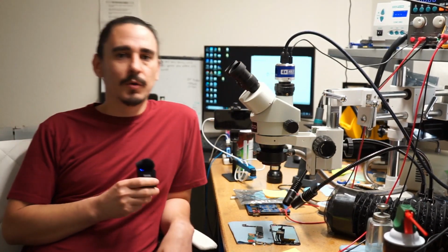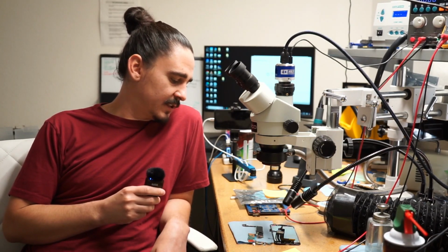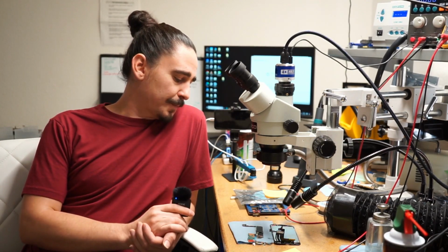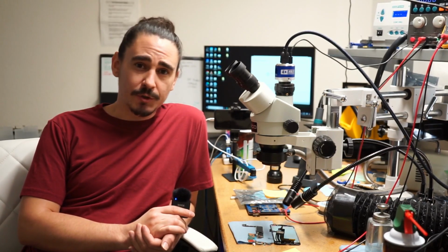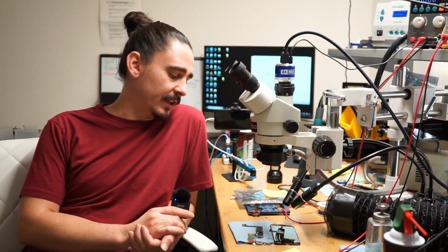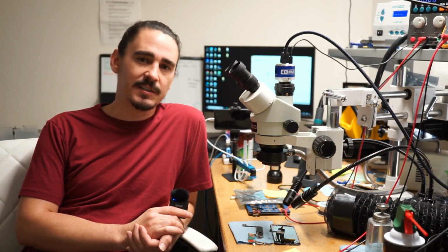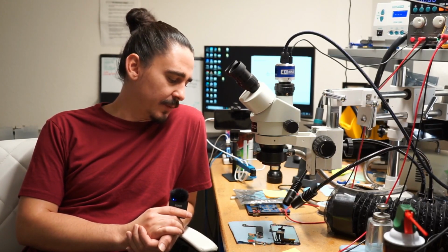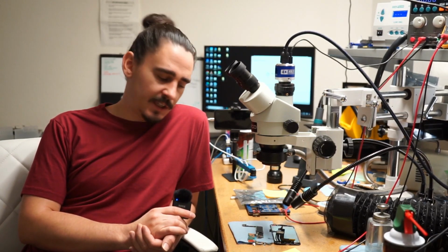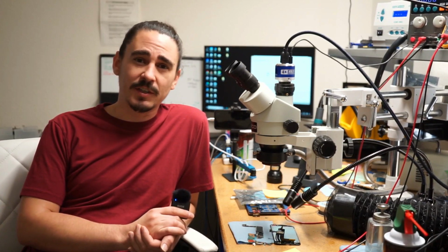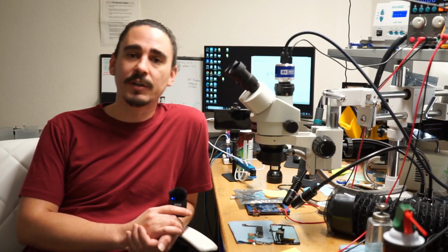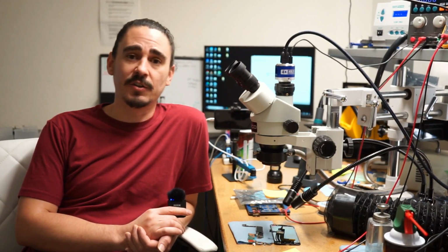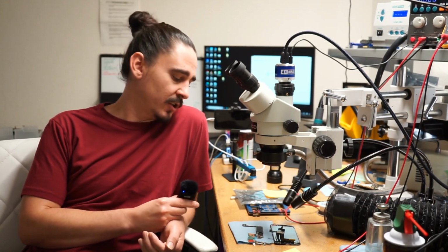And a couple takeaways from this board. So my amperage draw indicated that I had a power rail short, and the short was definitely in a spot that I wasn't anticipating. It was caused by long screw damage. Another key takeaway is you can't always listen to your customers, because the customer said it didn't go anywhere and that this phone died on its own. And this is obviously technician damage.